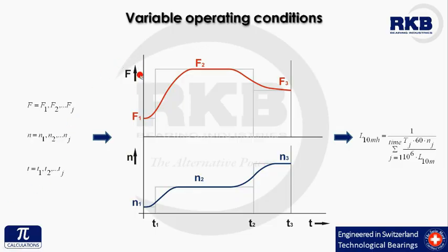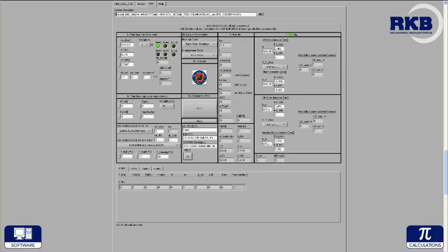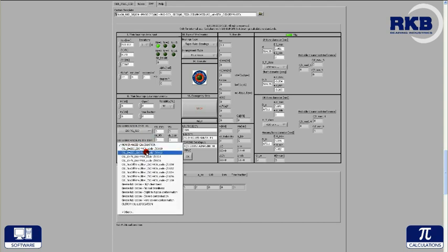Heavy loads generated by shocks and overloads diminish the bearing life at a faster rate than the normal load regime. Even if the occurrence of these loads is relatively rare and limited to a given operating time fraction, they must be considered. The operating temperature is inserted in the software together with the type of lubricant and filter type.